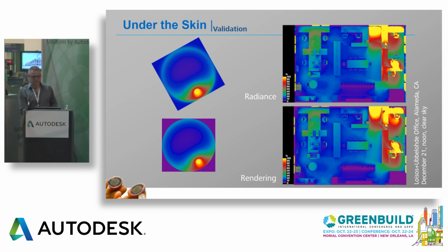We can see a couple of differences, which is what we'll be fleshing out in this validation project we're working on now, where, for instance, here, the way that Radiance and the way that the lighting analysis tool models glass is slightly different. Radiance uses a single plane and then a distribution based on a BSDF or a standard distribution. We actually model the thickness of glass and model the physical way that light moves through glass and refracts and distributes. So we've got a little bit of different response right near the glass surface. But in general, we're getting very similar results.